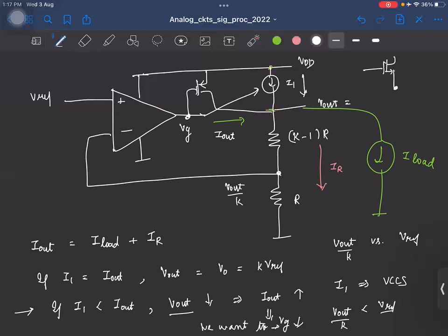Because with the PMOS, your source is fixed. Thus, by tuning gate voltage, we can very easily control the current. But with the NMOS case, the source voltage is connected here. So even if you change this, source voltage will also increase. You might not be able to control the current so much. Okay, so PMOS is a better choice here because one end is fixed.